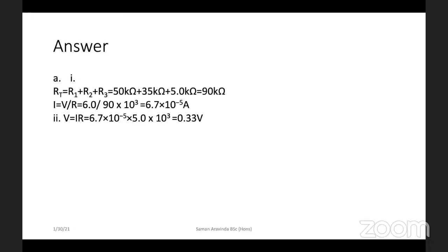So, part B. State and explain what happens to the reading and the voltage. The intensity of light incident on the LDR increases, so the resistance across the LDR will reduce. Then the voltage drop across the LDR reduces, so the voltmeter reading will increase.